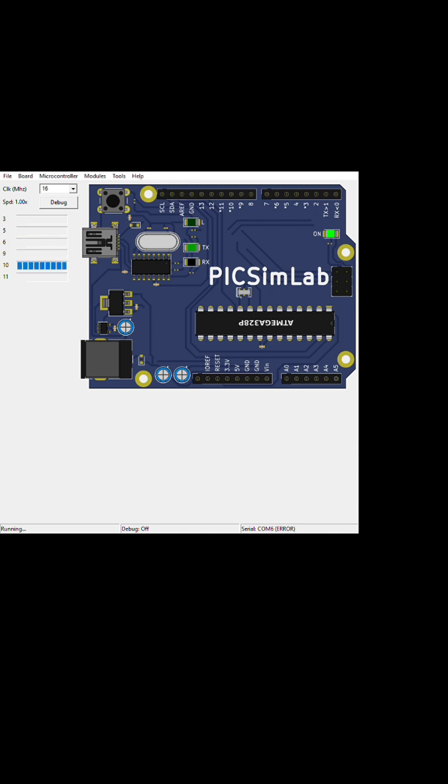So these are the sensors which we used in the node 2 implementation, like the DHT22, PIR sensor, and a module used to connect to the cloud, and the LDR sensor where we will be seeing whether it is dark or not. This door switch is used to detect whether there is any interruption in the factory, and this ventilation relay will say whether there is any interruption related to fire. So this ventilation relay will be using the fans.